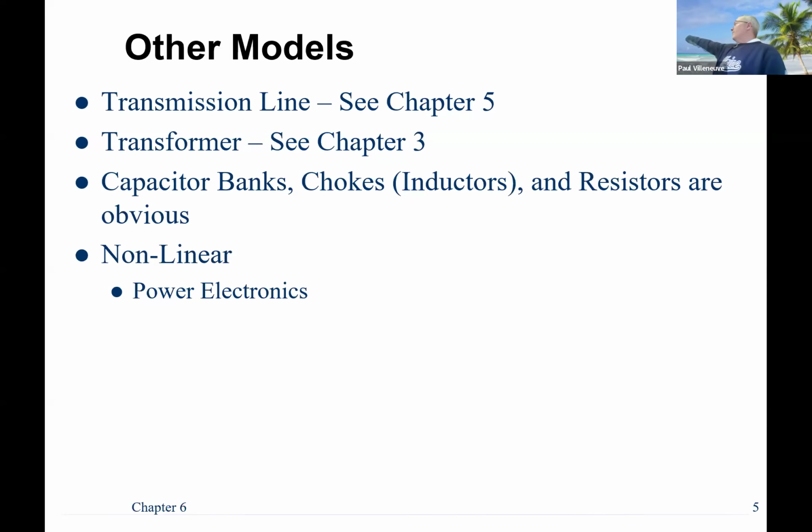I did a project many, many years ago for Harvard, and in Boston or Cambridge they had massive amounts of fault current. One of the resolutions there was actually to put incoming reactors that knocked down the amount of fault current. And you didn't put a resistor because a resistor is consuming real energy, right? It's wasting joules because it's just generating heat. A reactor is going to knock the fault current down, but it doesn't actually waste any energy, right? Because the power is sent back. That's pretty much the only time I've seen reactors actually in the power system.